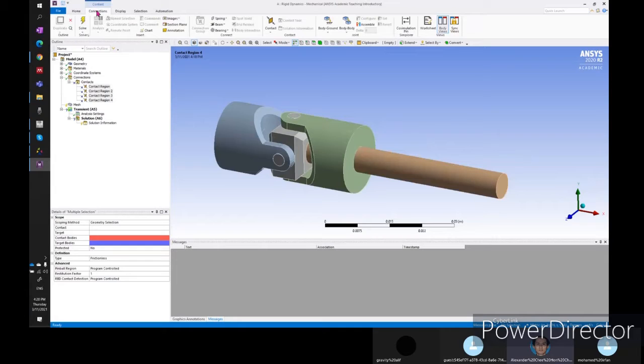Now I would like to set up the joint to define how it is. If you don't set up the joint, even though they are now assembled together, in ANSYS they will actually have no relation at all to one another. It just looks like they are joined together, but when the simulation starts, they will all depart and go into pieces their own way, because we did not define their relation. We did not define their joint. Once the simulation starts, we call all this a black box.